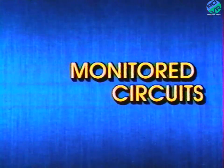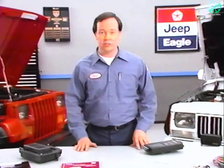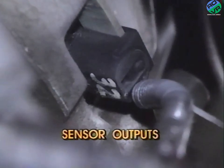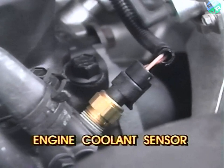In order to fully understand the onboard diagnostic capabilities of the fuel injection system, you need to know what systems the engine controller monitors and what it doesn't monitor. The engine controller can detect certain fault conditions in the fuel injection system. For example, the engine controller can determine if sensor output is within a proper range and if the circuit is open or shorted. It can also sense whether input devices, such as the engine coolant sensor, are hooked up.